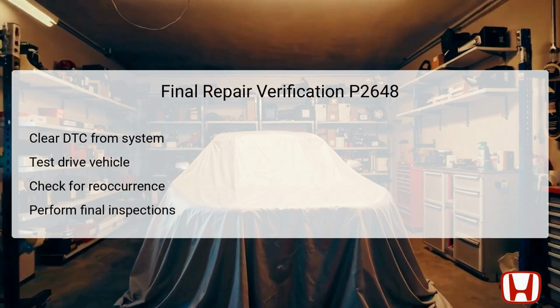Next, take the vehicle for a test drive under various driving conditions to ensure that the repairs hold up. Observing the vehicle during this time allows you to check for any signs of reoccurrence of the error or related symptoms. Concluding with a final inspection of the solenoid and electrical connections will help confirm that everything is in proper working order before returning the vehicle to the customer. This comprehensive verification step is vital for ensuring the reliability of the repairs made.